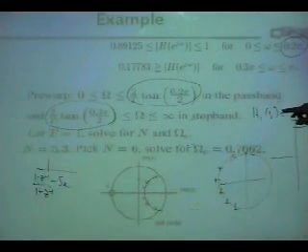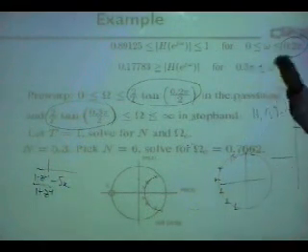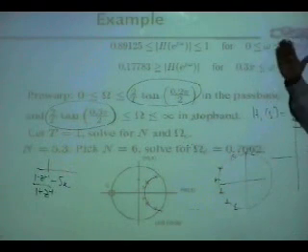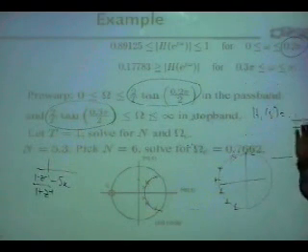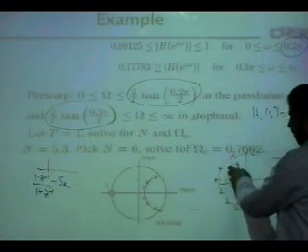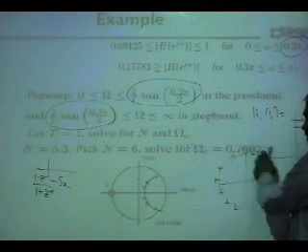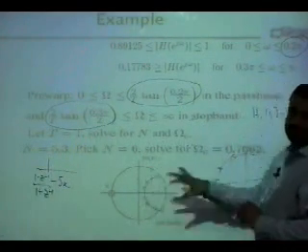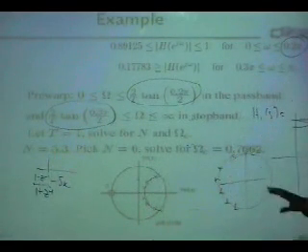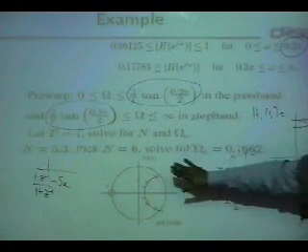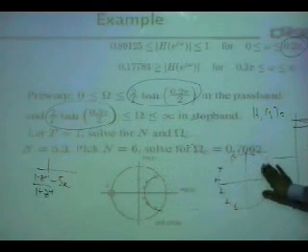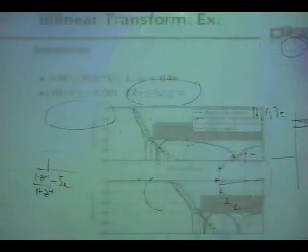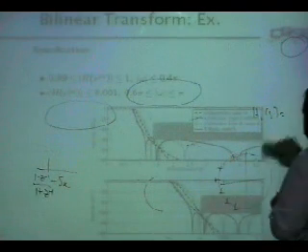Even if you go in MATLAB, use a Butterworth filter, you will find all the poles are placed on a curve. That is because the poles here are on a circle, and once you translate, they appear something like this. Okay? But this circle has nothing to do with the unit circle in Z domain. This is in S domain. Okay? So I think this is where I conclude.